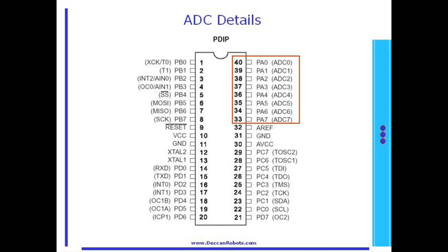Imagine that we have configured the ADC 0 channel to read a voltage range with 8-bit output format. The lowest level of input analog voltage will result in a numerical value of 0, and the highest allowed input analog voltage will generate a numerical value of 255 as the output of the ADC.